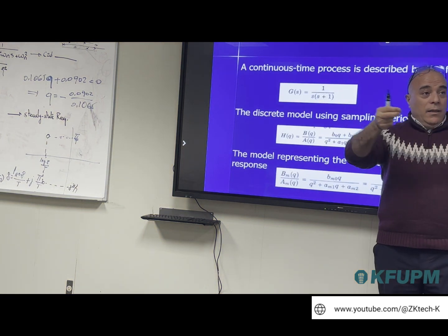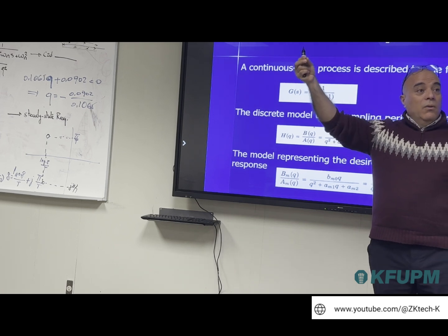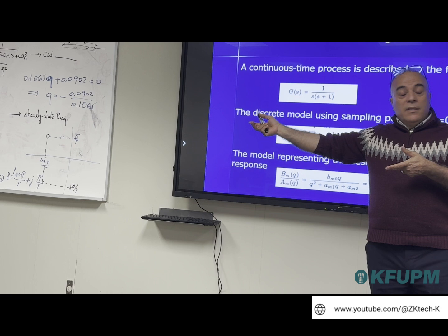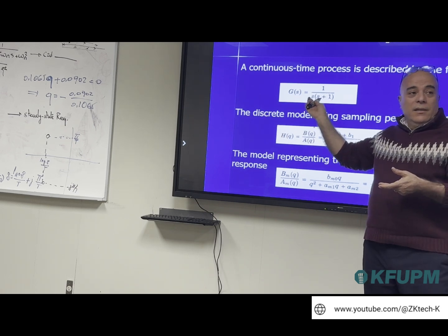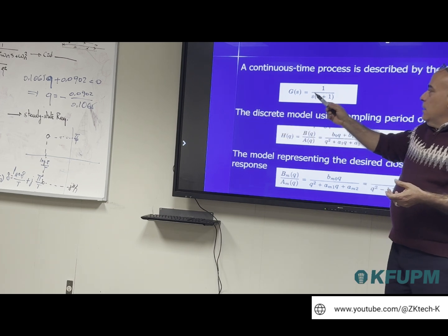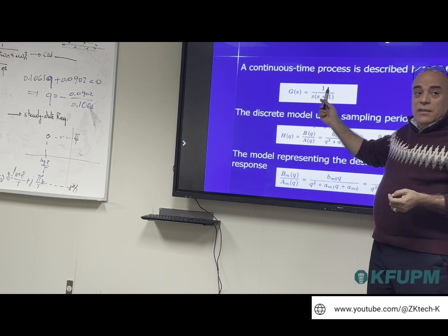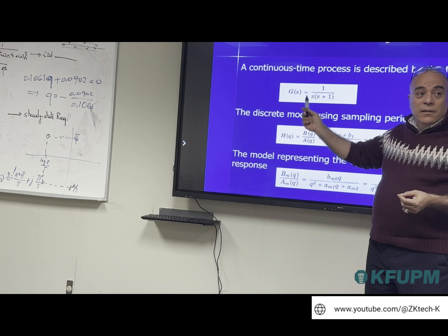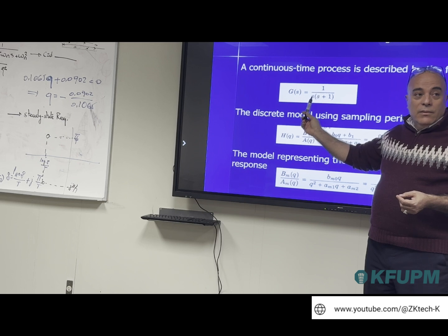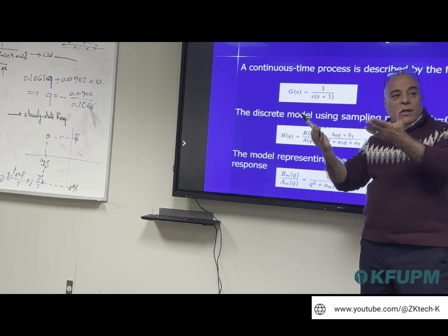So if I do the pole zero matching from continuous to discrete using e to the power sT, I will find 1 over z times z minus 1 times z minus e to the power minus 1 times T. But this is one possible way of discretization. Another way is to say that we have two zeros at infinity. 1 over s squared is also 0 at infinity. So I would like to replace s equal to infinity in the top and see what will happen.